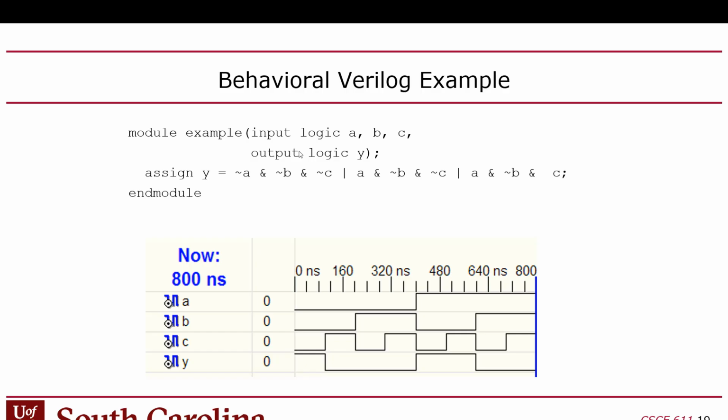Yes? Don't we schedule the clock time according to the critical path delay? Yeah. The longest delay. That's right. So in this class, when you simulate the behavior, you can set the clock to whatever speed you want. It doesn't matter. When we deploy this on the FPGA, though, we have this little bit of a cop-out where we're going to use a 50 megahertz clock.